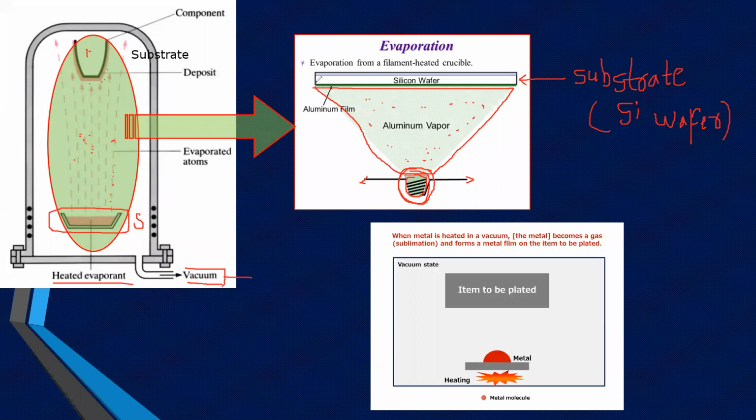Now that green part of the shaded region is nothing but an aluminum film, in the range of some micrometers to a few nanometers. It depends upon our application and our interest: how thin a layer we need for further purposes. By that requirement, we can evaporate the aluminum particles and deposit them onto a silicon substrate.